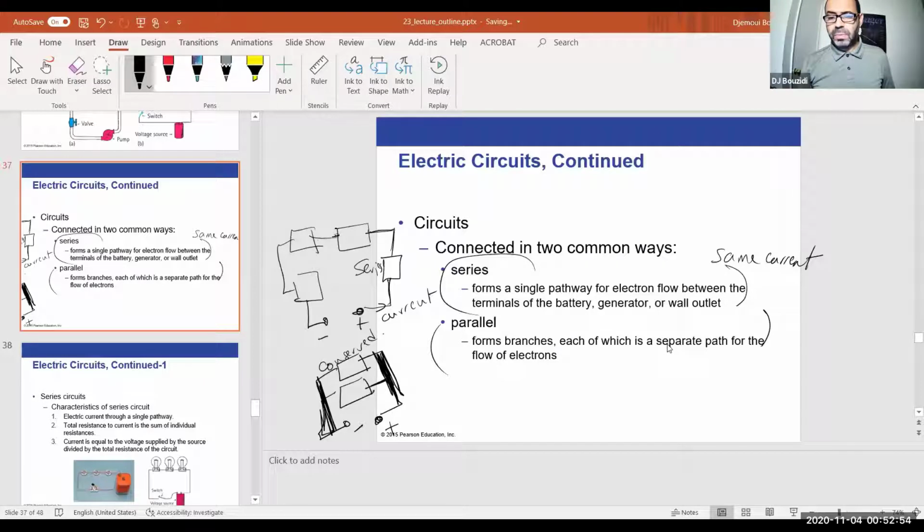So there is the same difference of potential across the two devices, okay? So parallel is, on the other hand, same voltage. And that is your item 2 of the discussion today. Series connections, same current. Parallel is the same voltage.